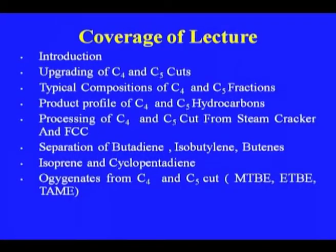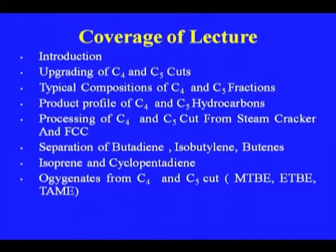Next, the typical composition of the C4 and C5 fraction, because many of the products we get from C4 and C5 are very important, valuable petrochemical feedstocks. We will discuss in detail the product profile of the C4 and C5 hydrocarbons, and then the processing of the C4 and C5 cut from the steam cracker and the FCC.